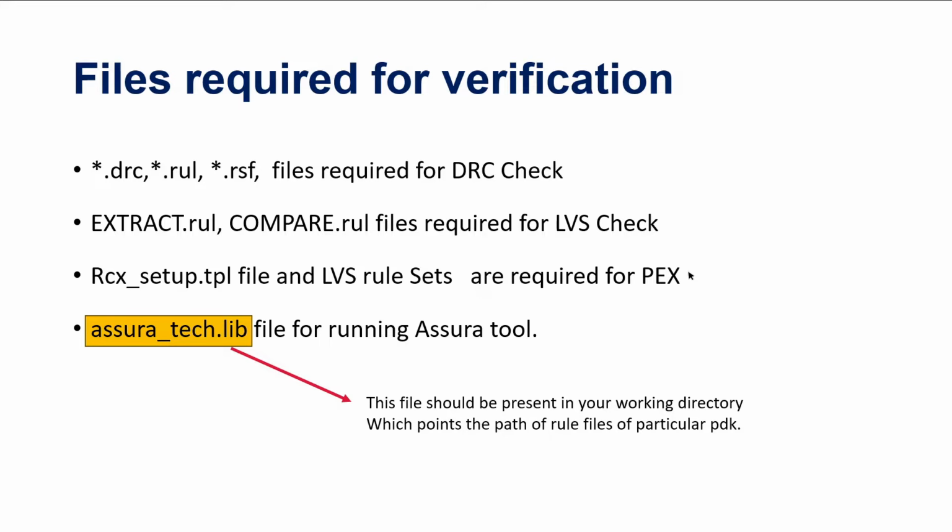And one more file for Assura, the TechLib file. This file has to be configured in the working directory, which will point to the path of the rule file of a particular PDK. So let's move on to the demo and see how it works.